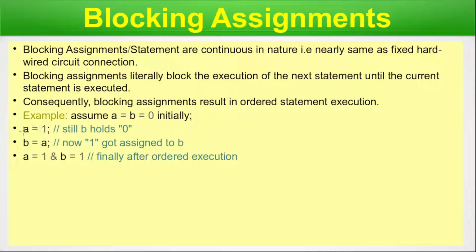Why do I say the playhead in time? If we include a hash delay here, the time playhead will wait for the delay to pass and then it will assign. Here you can see the delay is by the playhead in time. Otherwise all the statements will be at the same timeline point and the playhead will play all of them at once.